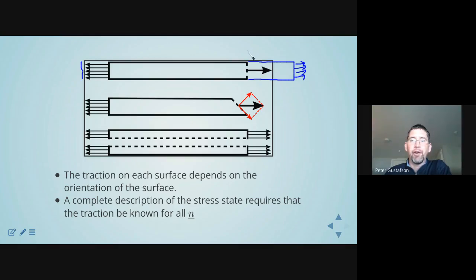Now I've taken my imaginary cut, and what you see here in black and then dotted lines indicating this imaginary cut that I've made on the internal surface of my axially loaded member, I think it's relatively easy to recognize that equilibrium requires there to be a reaction force.